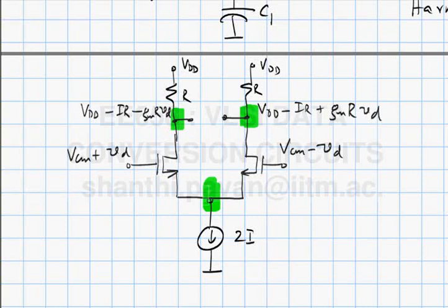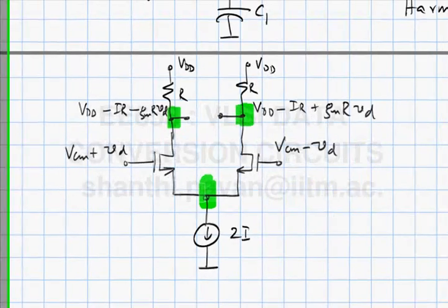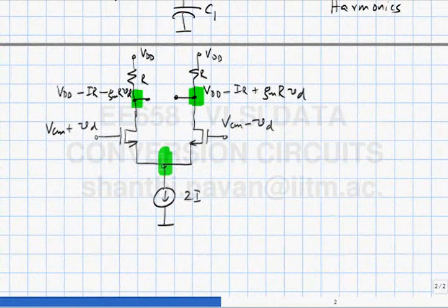So in this manner you do have differential gain, but you have no common mode gain, and you have CMRR and all this other stuff. But the bottom line is that if I yank the common mode of the input up by a little bit, nothing happens to the differential gain at all, because the quiescent current flowing in both these transistors is the same.